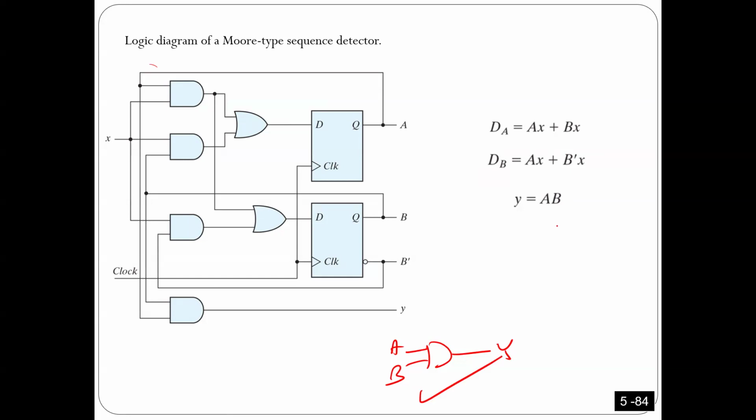And then after that, when I have this is A and this is GA, and then here you can have OR, and then you can have here N, you can have here N, and then you can repeat A again, B again, X again. So when you repeat A multiple times and X multiple times, you make the drawing much easier. You get what I'm saying? I know every A should be connected together using one line. I know that. And that's what you have to do when you implement the circuit.